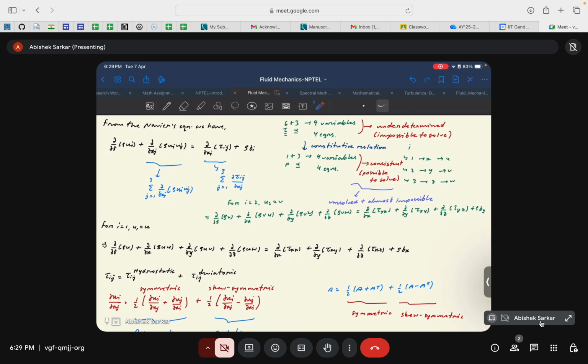Again, this is imposing the condition of the fluid being Newtonian and the Stokes hypothesis. Let us not go ahead of ourselves, let us go step by step, but this is what we do. And you can see that even in its current form, this equation seems quite notorious and very difficult to solve. So you know the complications that arise while trying to solve the Navier-Stokes equation.